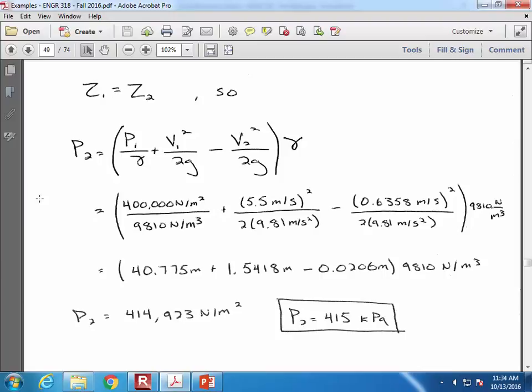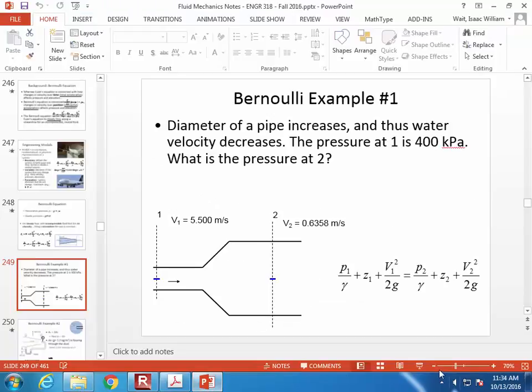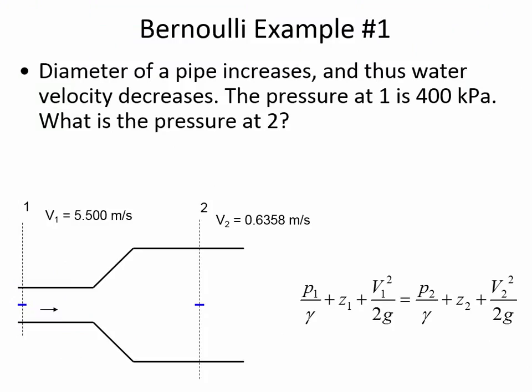That is a little counterintuitive, right? That's a great question. Let's think about that. Normally, if you just thought of it in qualitative terms without an equation and without a calculator, maybe your brain would think, well, you've got this enclosed pipe and it's all bottled up, and then the water opens out and now it's free, and so the pressure should decrease because it's less confined than before. Conceptually, that's oftentimes the idea that students have. But it's just all about the energy, and where is the energy and where can it go when there's a change. We know that expanding that pipe must slow down the velocity.